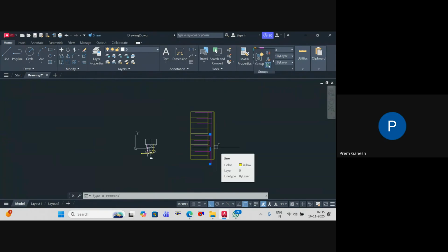No, we will do zoning for the reduction of the pressure to get the minimal pressure at the end point. In the same way, now we are designing these sprinklers, based on my hazards and the square meter. So when it reaches the 30th floor, my pressure will be high in the vertical line.